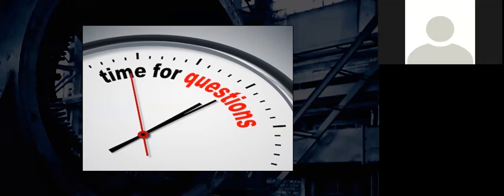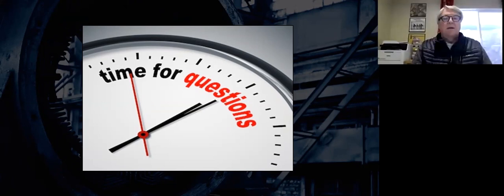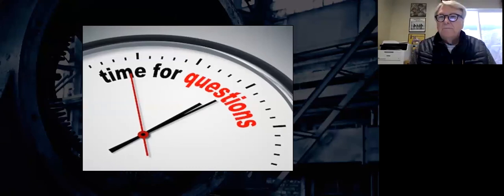Okay, it looks like we have one last question here. Or a couple came in. Do arc flashes differ inside and outside? Yeah, no, same thing. It's the same thing whether you're inside or outside. Now, as we talked about on the limited approach boundary, if you go outside and you've got a cable, let's say, going from your building to the utility pole, well, that cable can swing, and therefore we call that a movable conductor. So now your limited approach is 10 feet rather than 3.5 feet. But no, the rules are all the same outdoors and indoors.